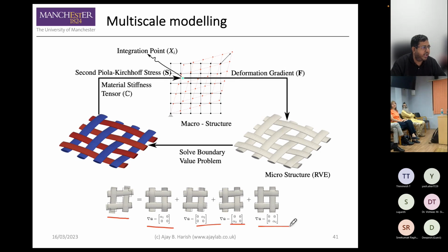So that was my idea in a way, to decompose our deformations and say it's like a superposition. Let's say I have alpha 1 into delta U1, plus alpha 2 into delta U2, plus alpha 3 into delta U3. So there are these alphas here. Can I decompose them into 4 different deformations and superimpose them? So I take my deformation gradient and separate it out into 4 different modes of deformation, and then put them all together to construct, let's say, the displacement vector for me.